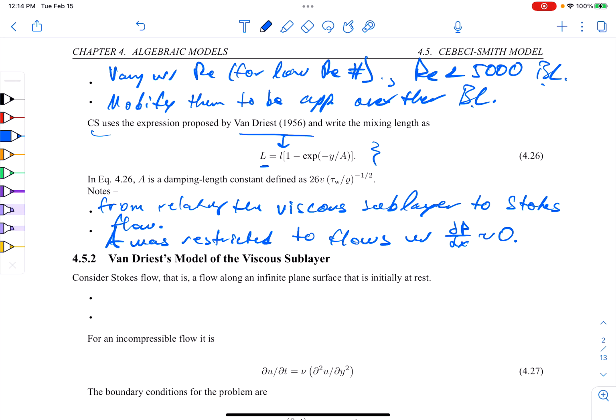This means that just taking Van Driest's modification to make a smooth length scale, it's limited. On real aircraft, you have very large pressure gradients that are mainly due to the curvature of the vehicle, because real vehicles have sometimes strong curvature, especially near the centerline axis. And those pressure gradients became very large or very small. And so just using this model as it was didn't work at all.